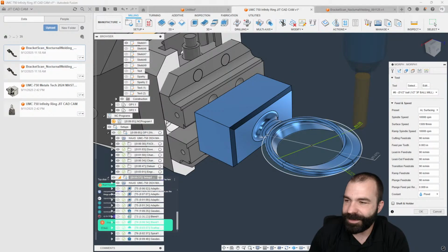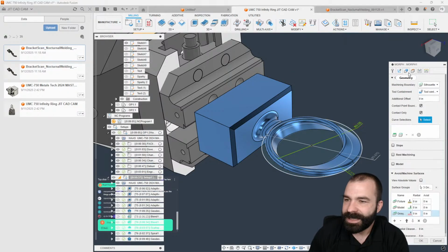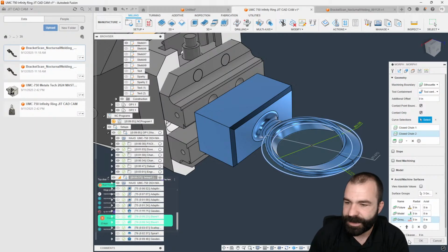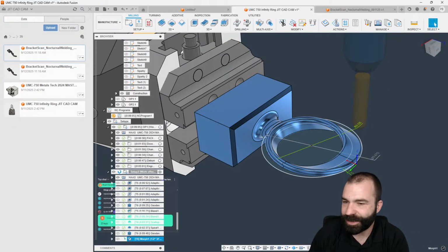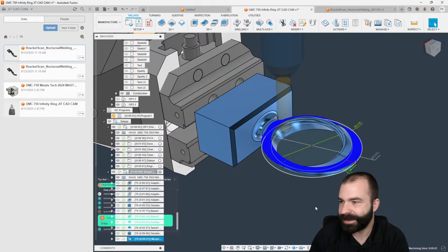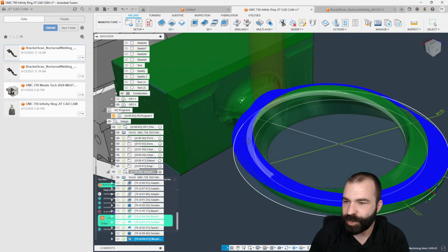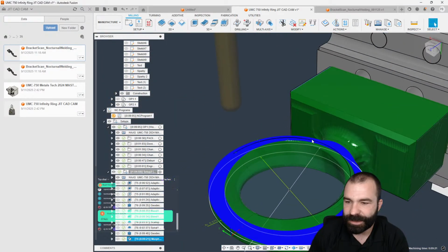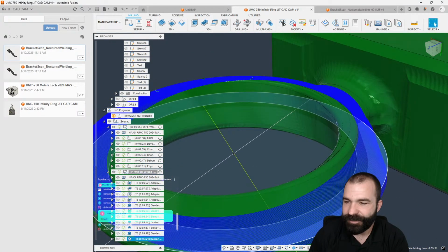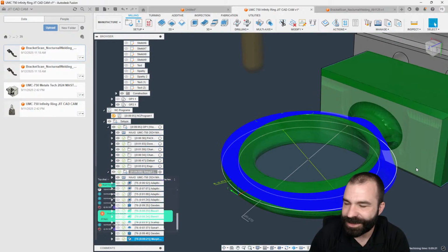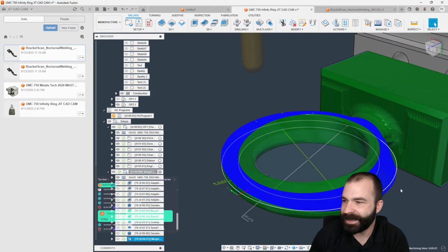Stuart with the 5 in chat. Let's go, Stuart. So again, on the normal Morph toolpath, what it's looking for is a curve selection. So I'm going to go ahead and give this 2 curves. Usually when it wants a curve selection, it always wants 2 curves. Now, again, here's a Morph toolpath following 2 curves. So again, it is looping around quite nice. Very overkill on the step downs unless you're going for something very, very nice.